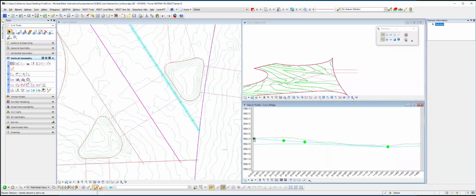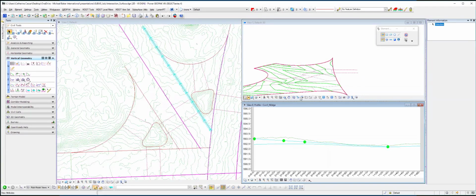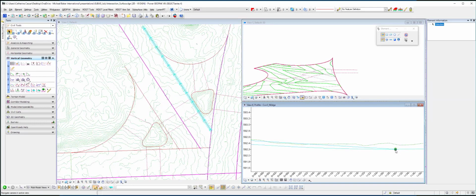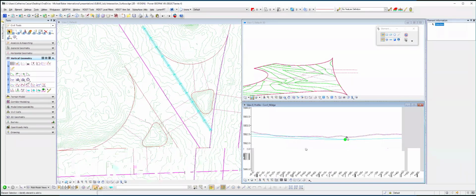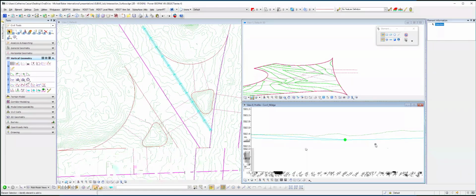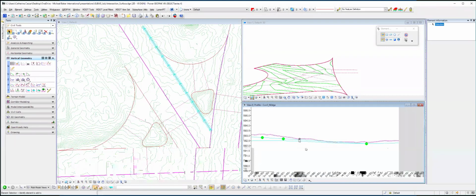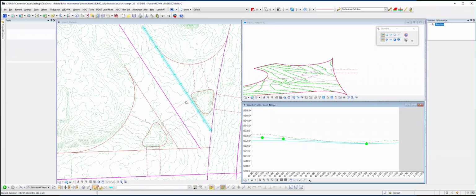So in this case, I'm tying into my edge. I'm tying into this control point as I'm warping the pavement here. I'm tying into this edge as I warp the pavement some more, and then making sure I'm touching back down here where my model needs to tie into the other model. And there'll be a small change in slope, but not bad. And this becomes my vertical profile.